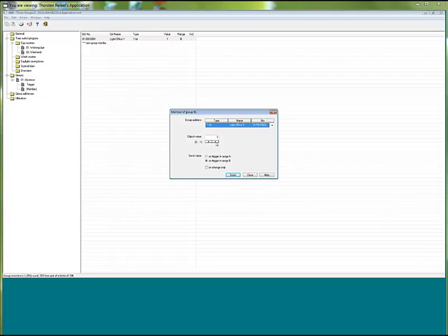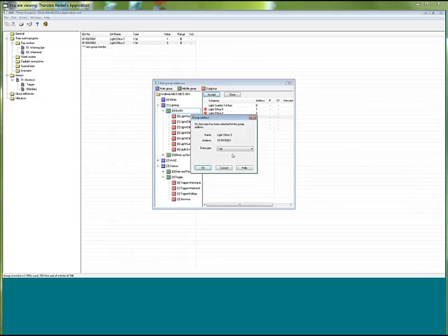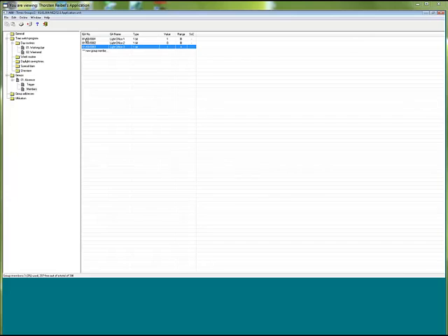Maybe the other light I would like to switch off, but also if I send an on telegram. But another function, whatever it is, light office 3, shall be switched on if there's an off telegram coming from the trigger, range A. So it's very flexible here, this creation of groups. So you see here the overview. I switch on the light if I'm in range B with a trigger on telegram, but I switch on the light in office 3 with value 0 of the trigger. So a lot of options you have here.